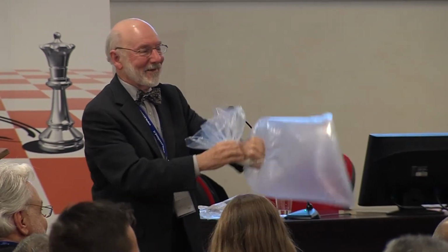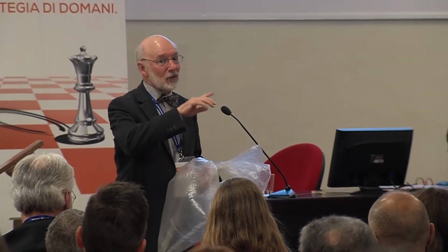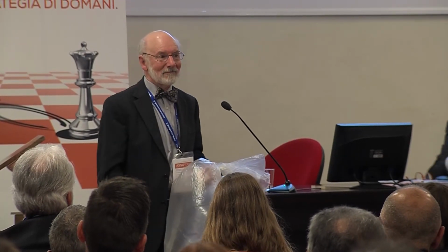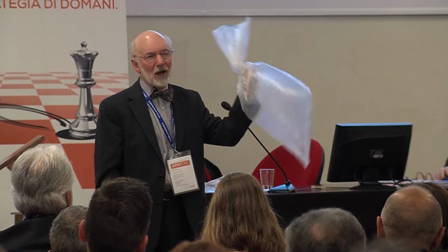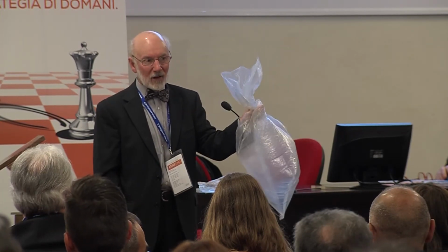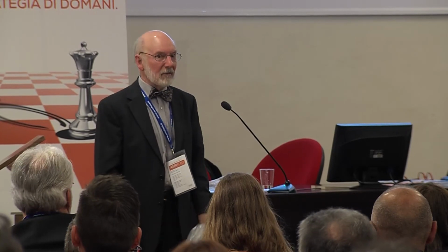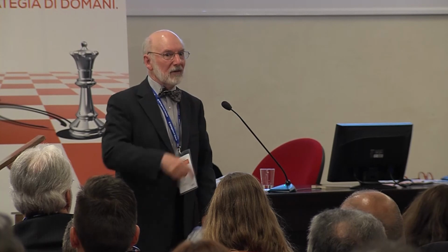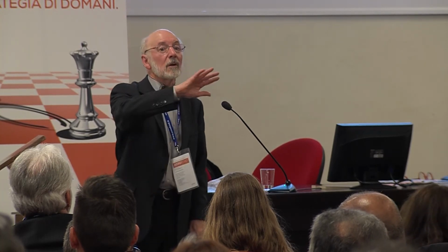Okay. You can see why your castings are no good. They are full of air and oxides and bifilms, and you never ever make a good casting pouring down conical basins by gravity. It's not possible.